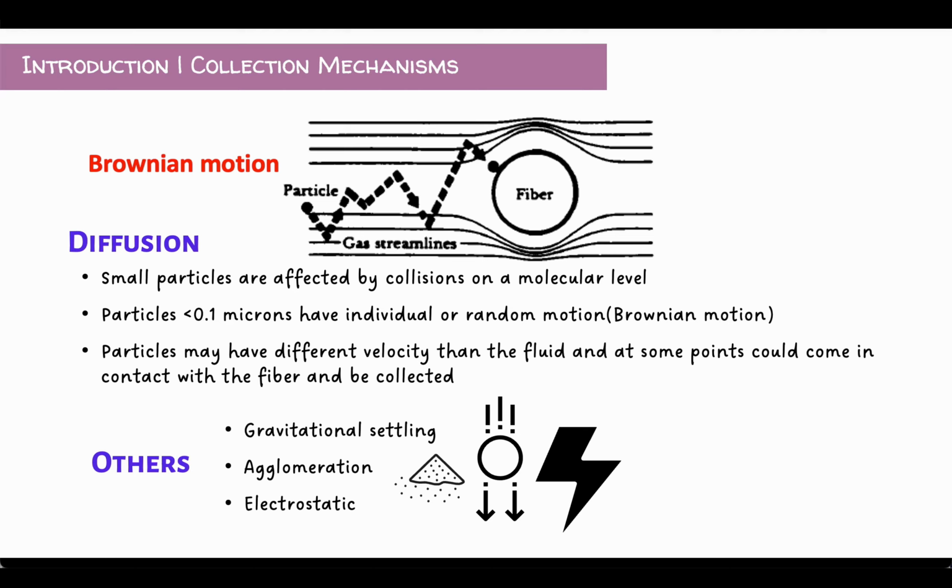Particles are also collected by gravitational settling. Relatively large particles are overcome by the force of gravity and fall into the baghouse hopper. This force is particularly important when dust-laden gas enters the baghouse through a hopper inlet.